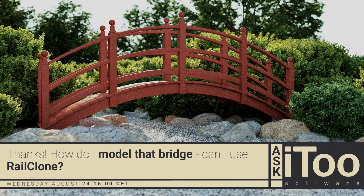In fact, all of these will be linear generators. So we'll bring in a spline, pick a spline from the scene, can be any spline. And I'm going to create the planks, like I say. So segment, and then I'm just going to pick these planks and wire them to the default input. I don't want to slice the ends like this, so I will change the mode to adaptive, and just to be doubly sure, turn off slice.